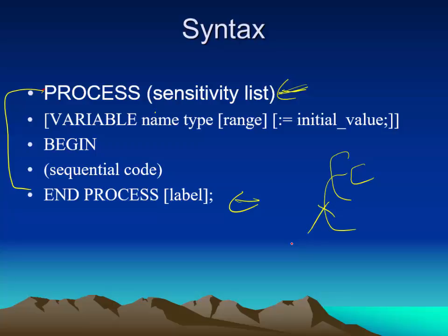See, this is where people get very, very lost and confused with VHDL, is that if I write code in C, it does one thing and one thing only at a time, right? It calls an interrupt, it processes the interrupt, and it goes back to the main set of code. When I'm writing VHDL, I'm designing hardware. I can have 3 different processes operating at the same time, along with combinational logic, all occurring simultaneously.